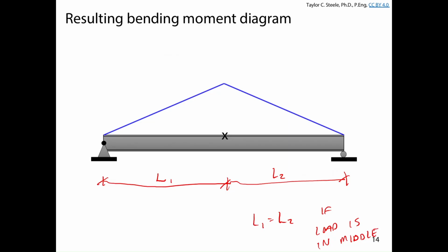So the presence of the joist there is first going to reduce the unbraced segment length. And if we reduce the unbraced segment length, we're going to increase our critical elastic bending moment. It also changes the shape of the bending moment diagram compared to what we talked about the other day. And so in this case, what we're going to do is break up this beam into the two segments that are unbraced. And so we're going to have a left-hand segment and a right-hand segment.